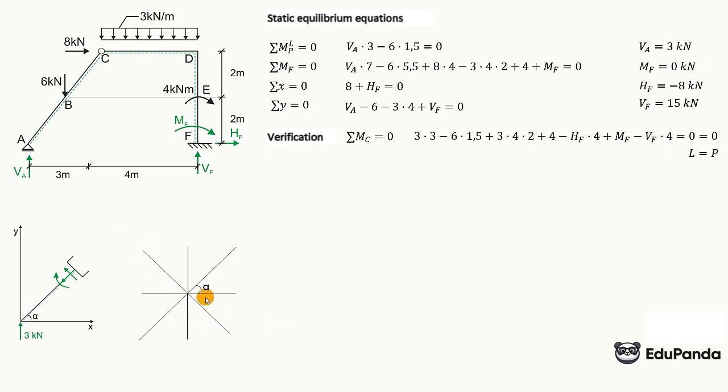And now from trigonometry, if we look at this right angle, here is the complement to the right angle, which is 90 minus alpha. We look at this because between the direction of the bar and its perpendicular is obviously a right angle. Here we have a complement to the right angle, so here must be a right angle, and so on. Every other angle will be angle alpha, so we can mark that every other angle is angle alpha. Now we will definitely have to resolve this 3, because we will be going from the left side to this slanted bar, so we will have to decompose this reaction, meaning this 3.